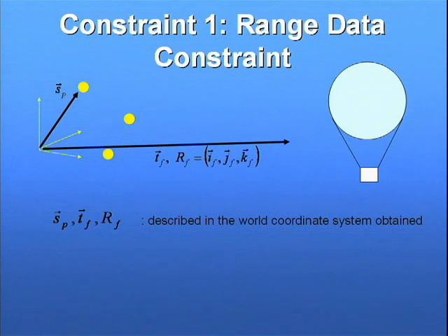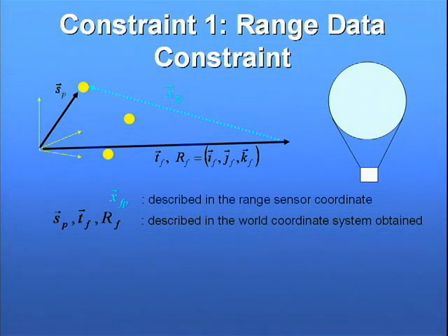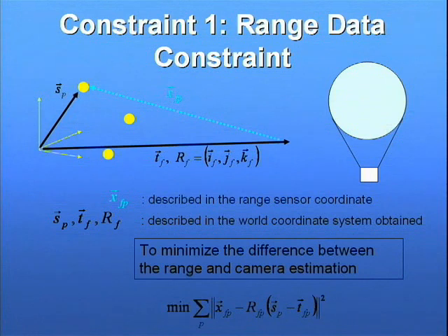Also, since this TV camera on the laser sensor is synchronized to the laser signals, we can also obtain 3D points with respect to this laser range sensor. They should correspond. Basically, data obtained by the laser range sensor should correspond to the range data obtained by the factorization method based on the motion parameters, if these motion parameters are correct.